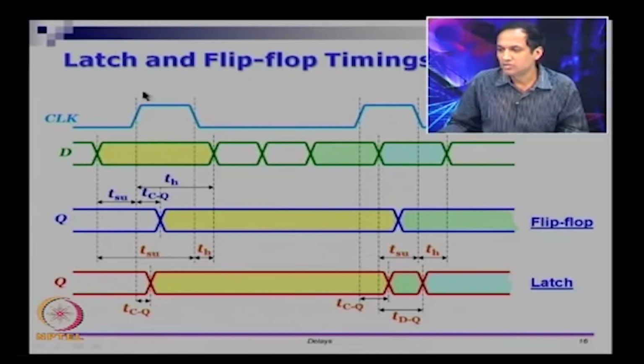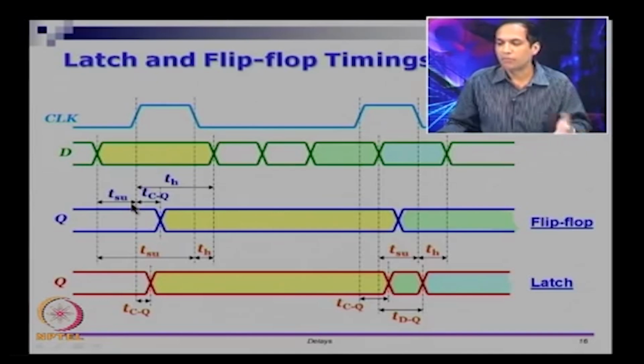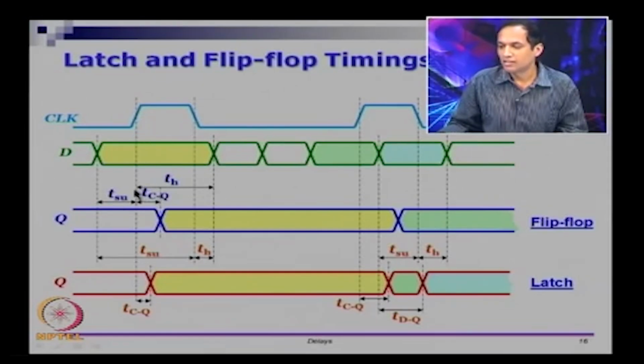So with respect to this edge, the data was kept constant for this amount of time, right. So it is a requirement from the flip flop, you have to keep it for so much time, that is the setup time, and once the clock edge arrives you have to keep it for so much time later. So, that is the hold time. So, setup time is time before the edge arrives and hold time is time after the edge arrives, and the propagation delay is